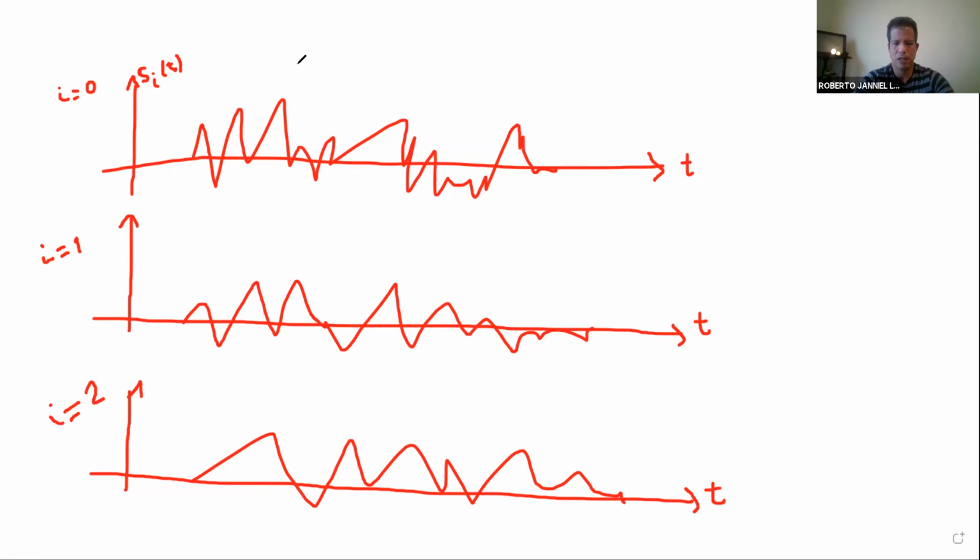For people in the radar community, who introduced this concept, you have here the time variable, and they called it the fast time. The reason for this is that in our case, it would be a signal that maybe has a bandwidth of, I don't know, 20 megahertz. I'm talking bandwidth, not center frequency. So you have to sample it at least at 40 megahertz. So that's a fast sampling frequency. So the signal is happening at a really fast time.